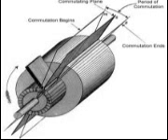A generator having a field winding connected in parallel with the external circuit is called a shunt generator, as shown in A and B of figure 9-16. The field coils of a shunt generator contain many turns of small wire. The magnetic strength is derived from a large number of turns rather than the current strength through the coils. If a constant voltage is desired, the shunt wound generator is not suitable for rapidly fluctuating loads.